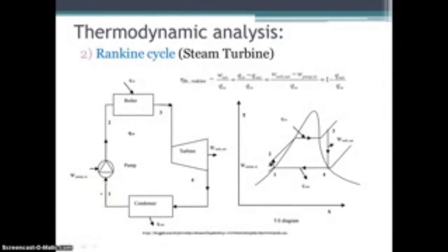The Rankine cycle is also one of the processes that use steam to produce electricity in a nuclear power plant. Water enters the pump as step 1 as saturated liquid and is compressed isentropically to the operating pressure of the boiler. The water temperature increases slightly during this isentropic compression process due to a slight decrease in the specific volume of the water, as shown in the TV graph.